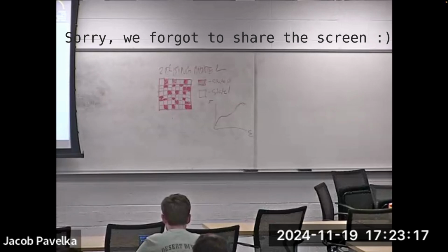And so at every material point, you think of this infinitesimal cube, and what are the forces acting on each face of this cube, and in what direction are they acting? So we define this thing called the stress at this point, and the material point next to it, what is it pulling on it, pushing on it. This is the concept of internal forces.